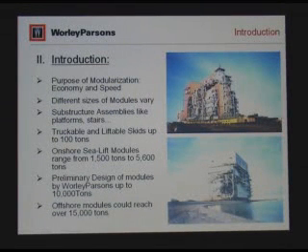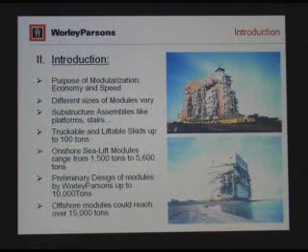What is the purpose of modularization, really? Why do we go for modules? We have two options. Either we can send all the steel and all the equipment and all the vessels, piping, everything to the North Slope, and they will put it together into a module like this. And that's very difficult because in the North Slope, especially in very cold weather, the window of work is only maybe 6 months. All the rest of the time, really, the people cannot work.